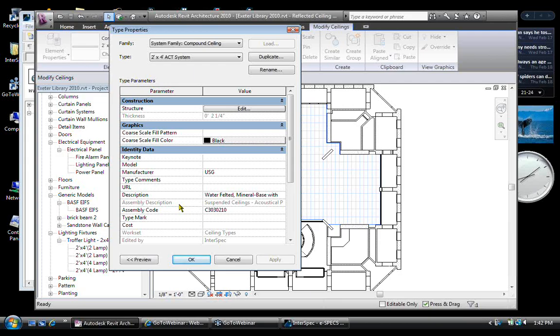It doesn't come with the program, so I have to make one. So in the process of making one of these components, it would be nice to put the fields in there at the time I create it, and then subsequently any modeler from then on that needs a recessed floor mat doesn't have to have all that extra time to put in these parameters. They've already been filled in for him, even though he can modify them and add to them. It makes the process a whole lot easier.